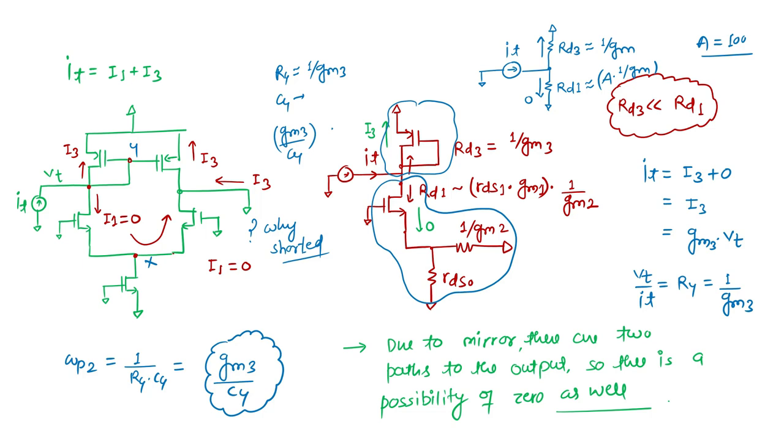So exactly whatever the amount of current is copied from M3 to M4, the copied current, which is I3, is coming from this ground terminal. Ideally the I0 is going here, and whatever amount is going here will completely go to ground itself. It will not flow across the I4. So I have considered ideally I1 to be 0. Even if it is a non-zero value, it will follow this path only. It is not going to flow through this M4, and whatever the amount of current I3 getting from here is also coming from the ground. So you can see this analysis in detail, and you can do this analysis on your own.